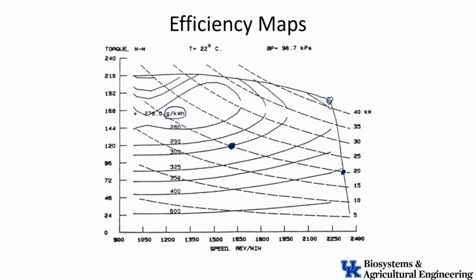Because a lot of times we will want to use it, and an engine will be set up for a certain peak power and for a certain application. So for instance, a lot of our equipment runs on hydraulic power, and we'll look at fluid power, we'll look at hydraulics. Hydraulics will only operate efficiently if I run them at a certain speed. So basically on a machine that's hydrostatically driven, I'm going to get in that machine, I'm started up, and I'm going to turn that engine to its maximum speed. And that's where I'm going to operate it all day long, whether I need all the power out of it or not. Because if I slow that engine down, the hydraulics don't work very well. They become extremely inefficient, and so the whole system is going to be more inefficient.